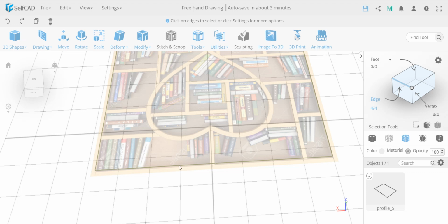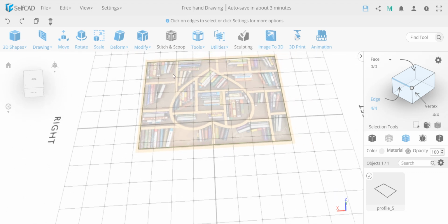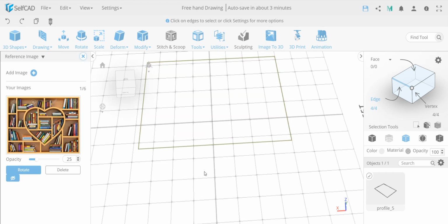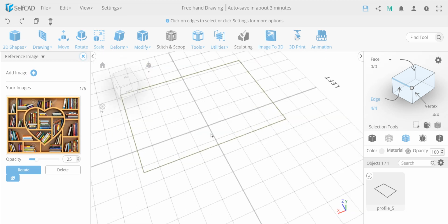It blocks my view. I think actually it did remove the line. Yeah, it still removed the line. I get only this. You see, let me go to view, reference image. I'm going to hide this. I can just delete them, but sure, you can actually hide them. You see, you don't have the center line. So this is always making the Boolean. And in a Boolean tool, if you have a line without anything, it's not a hole, it's just a line that needs to be removed.